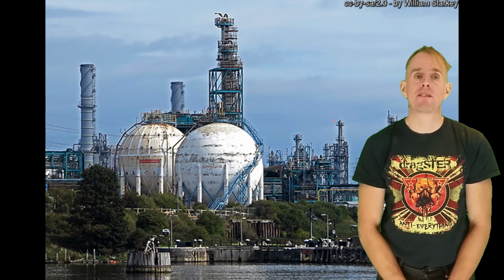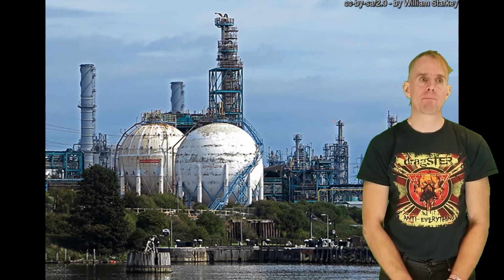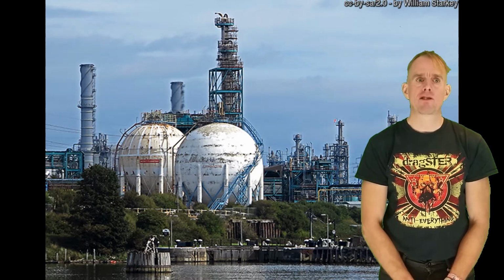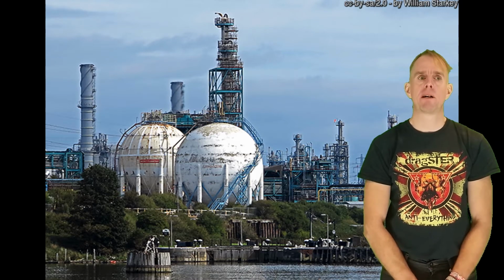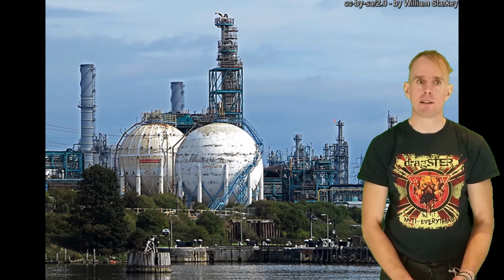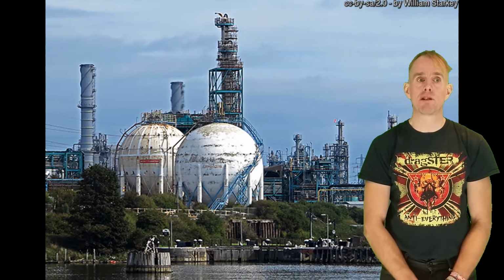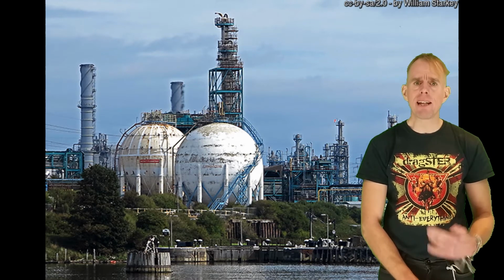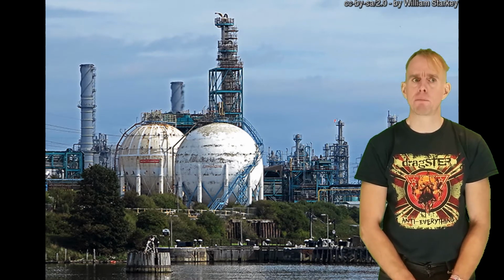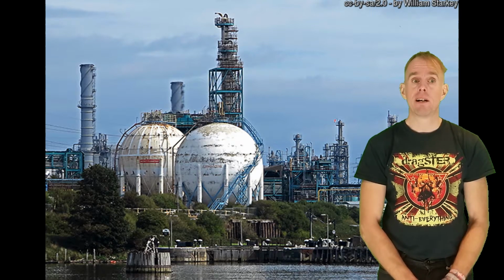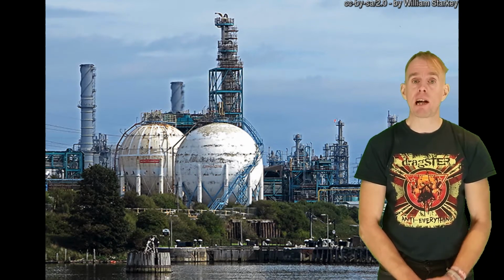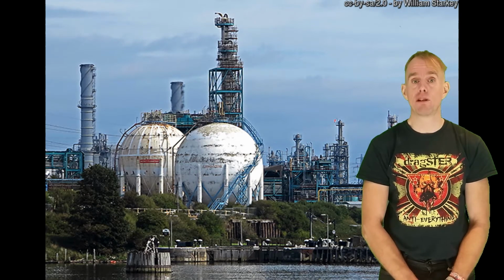Welcome back to this first lecture about chemical process design. The aim of this part of Lecture 1 is to familiarise you with the piping and instrumentation diagram, or P&ID, which is the most detailed drawing produced by the chemical engineer. In essence, anything that gets built on a chemical plant is shown on the P&ID, no matter how small the item is or how infrequently the item is used.